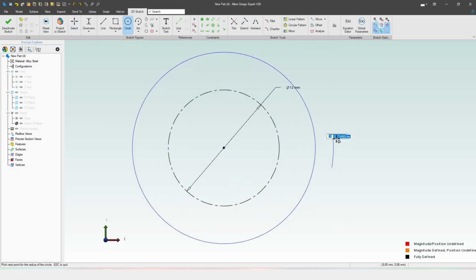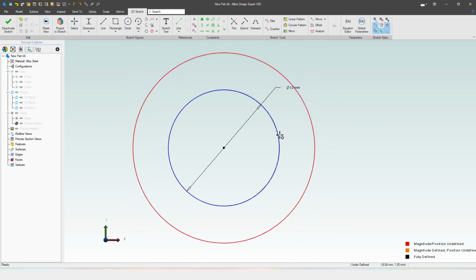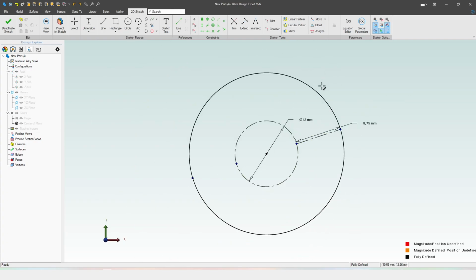Now we want an outer circle, and the distance of that outer circle to the inner circle is something that I will select. Bear in mind that this needs to be small enough so that you can make threads in tight spaces, but large enough to use the bonus trick I will show you at the end. So 5 times the P thread. Okay, this is large enough to use the bonus trick. I've been using it. It's okay. So this is the outer circle of our thread die.